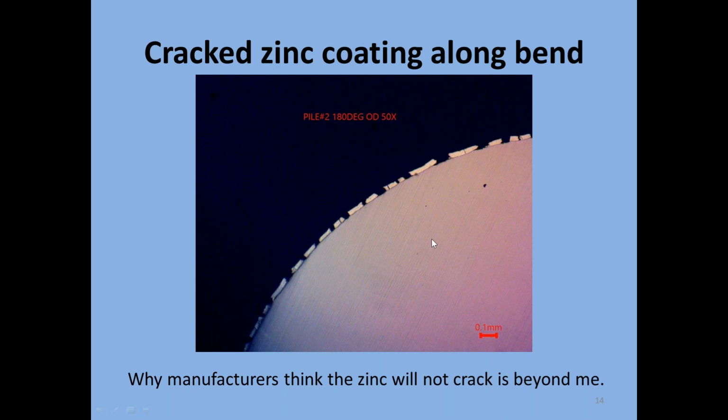It's great for atmospheric corrosion resistance in situations, but even then you have to think about, is there a lot of moisture, tropical, is the design going to pool water, or anything like that?